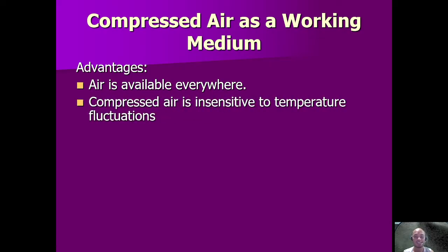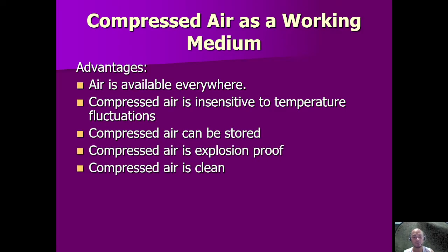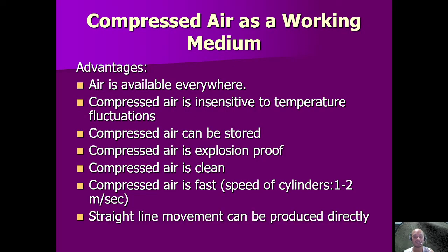So compressed air as a working medium has advantages: air is available everywhere. Compressed air is insensitive to temperature fluctuations. Compressed air can be stored and is explosion proof. It's clean, fast, and straight line movement can be produced directly.